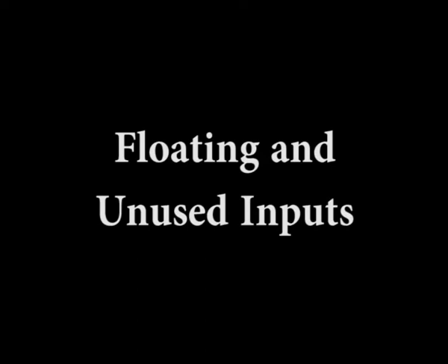Floating and unused inputs. The floating input of TTL family devices behaves as if logic high has been applied to the input. Such behavior is explained from the input circuit of a TTL device.